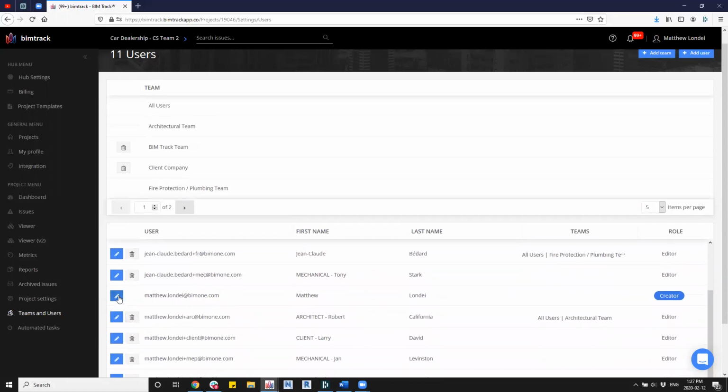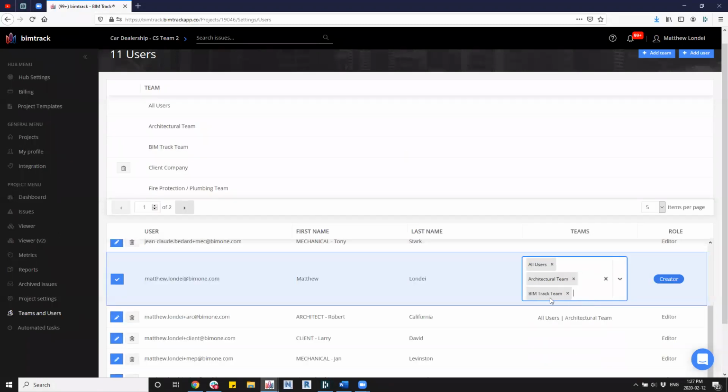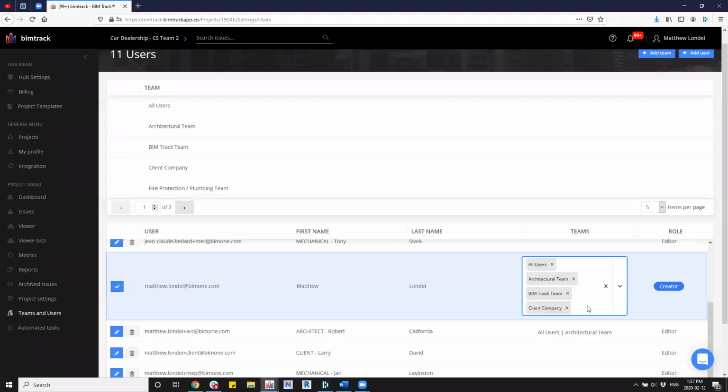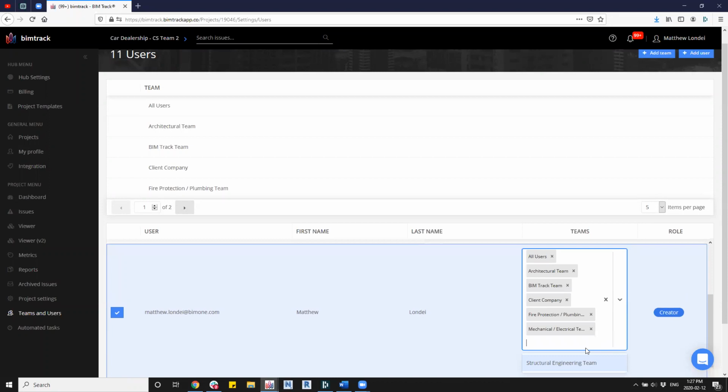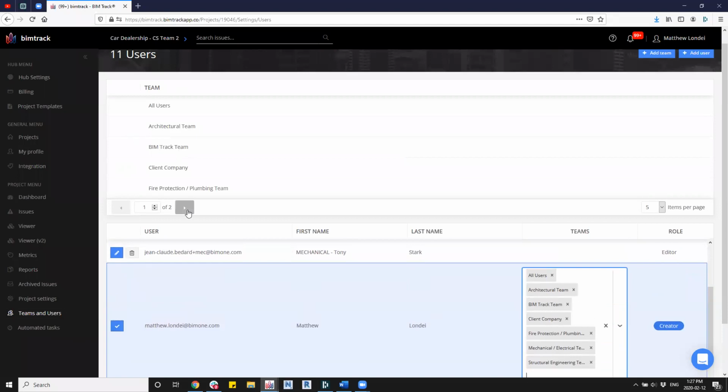Here's me right there. So I got to put myself on all users, architectural, BIM Track team. I am the only user on the BIM Track team, and I'm also placing myself on every single team that I created. So often we see the teams being utilized on a project, and that's great. And we see our project admins who have set this up, put everybody on their appropriate team, great, put themselves on their team, no problem, but have not put themselves on every single team. Now, it's not the end of the world, but it is highly recommended.